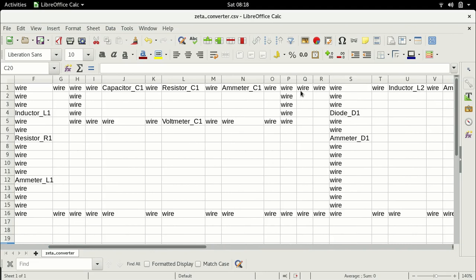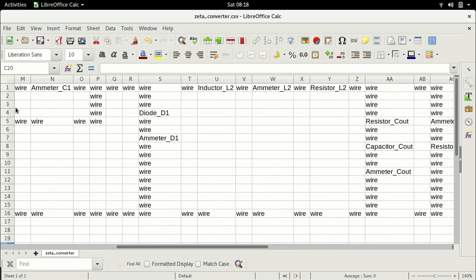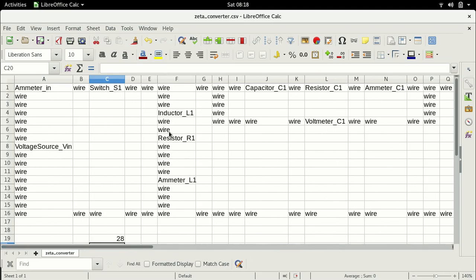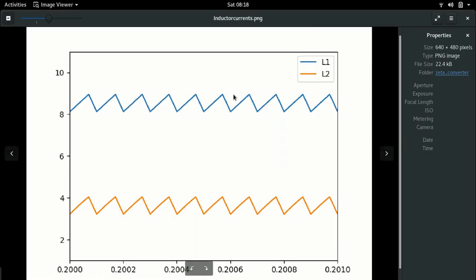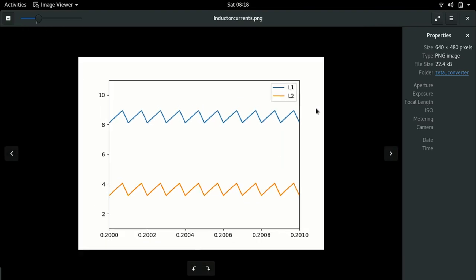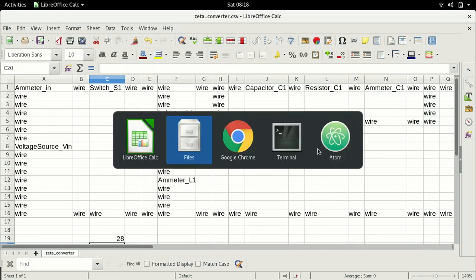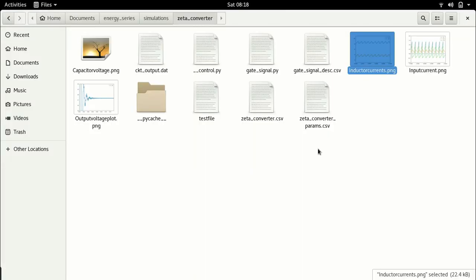It is being shared by all of them: the coupling capacitor, the output capacitor, and the inductor. Whereas here, the inductor L1 receives all the energy of the input, right? So this accounts for a larger current in the inductor L1 as opposed to inductor L2 when the duty ratio is larger, right?